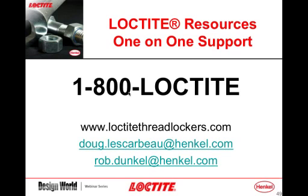All right. How many times can you remove the fastener before you have to reapply thread locker on, say, a 1/4 inch bolt? Our thread lockers are designed to be single use, which means every time they come apart, you would have to reapply them.